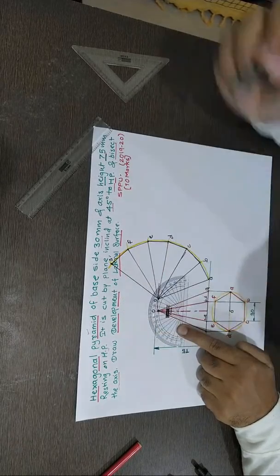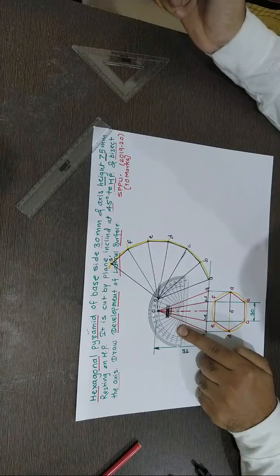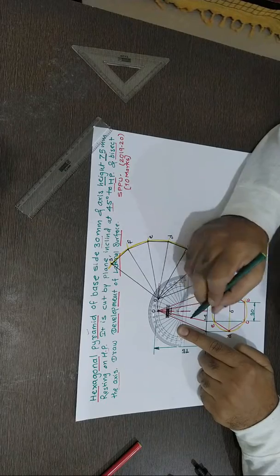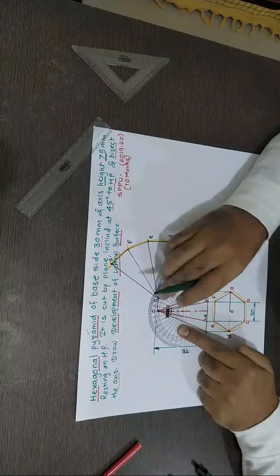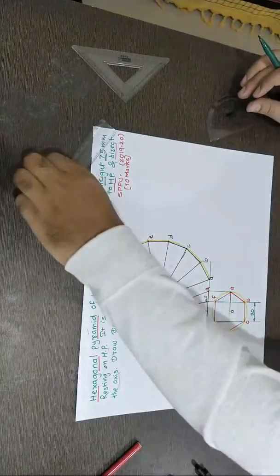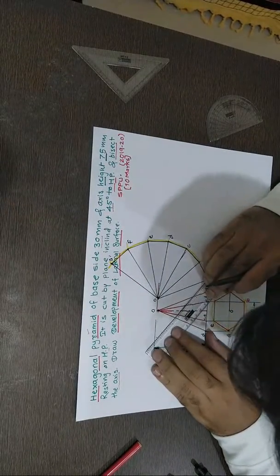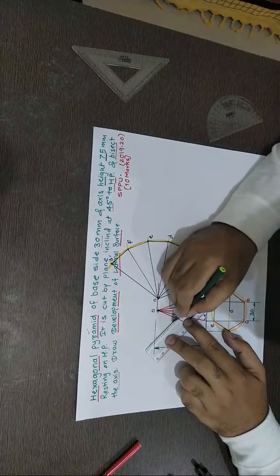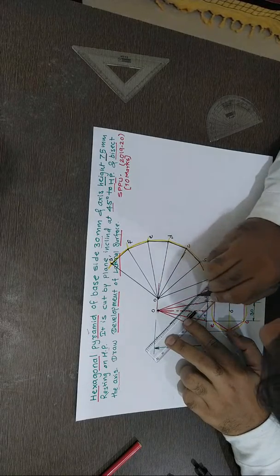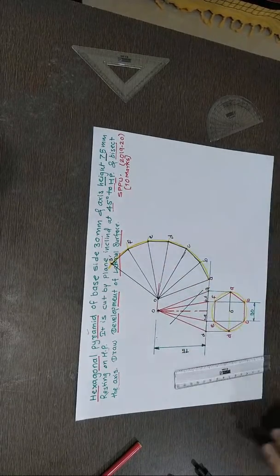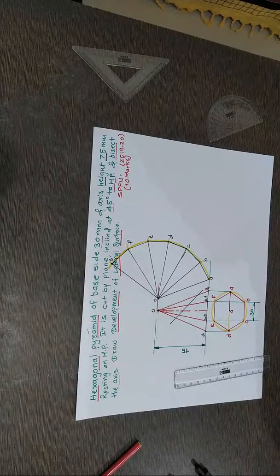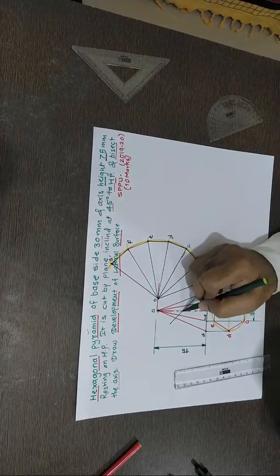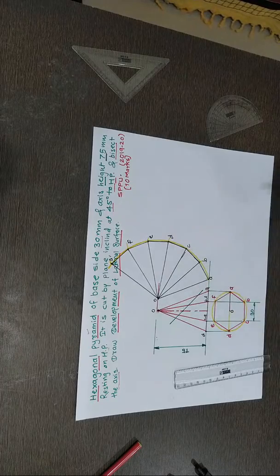This is a 45 degree angle, you can see clearly. So the point D is exactly the mid of the axis, and from this I am taking this 45 degree here. Clear? Now join this, which means locate the plane. Okay, fine. So now this is the line. I am drawing a solid continuous line. So now this is a plane which is at 45 degree to HP and bisecting the axis. This axis, its mid is here, so taking 45 like this.